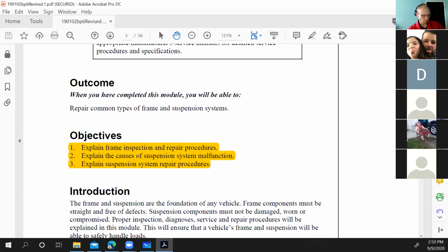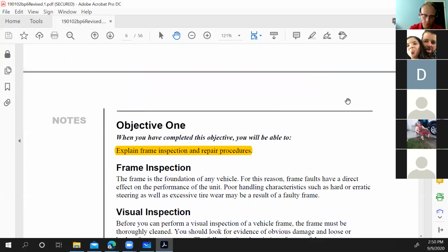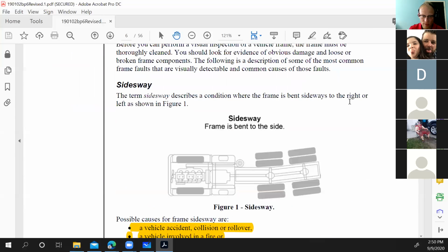How did you fix the frame that you drilled into? I didn't fix it, but I believe that they ended up getting it fish plated. I think it was 16 inches in either direction of the hole that I drilled. Oh yeah, in this ILM, I'll talk about all of these different repair procedures when it comes to frames.